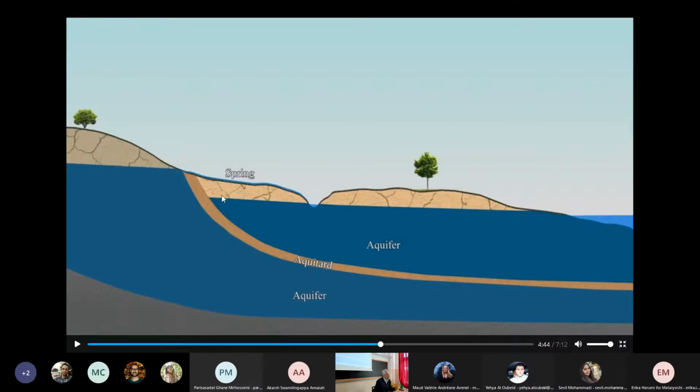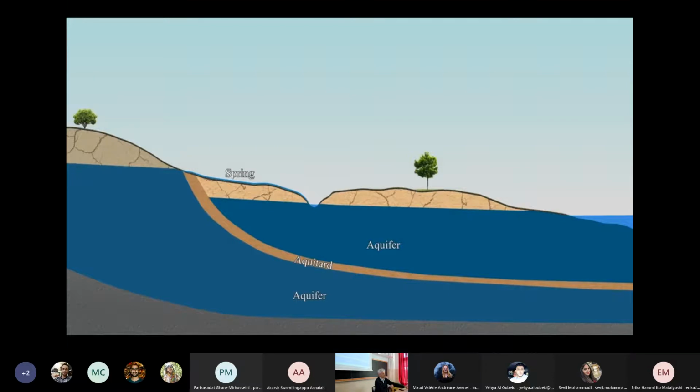So basically this means that the confined aquifer, after the intersection on the left here, is directly recharged by infiltration, but very far away, which means that water takes a long path from infiltration to pumping, which makes the water protected, because the soil is like a filter. But still, we have to take into account that this confined aquifer has a recharge that is very slow, if it is recharged at all.